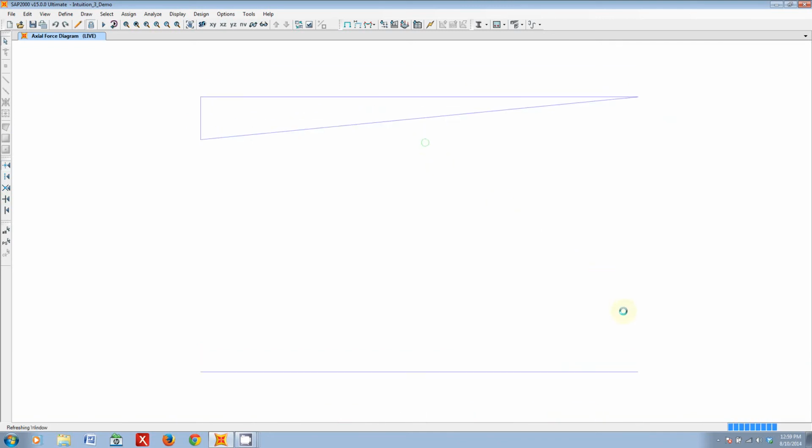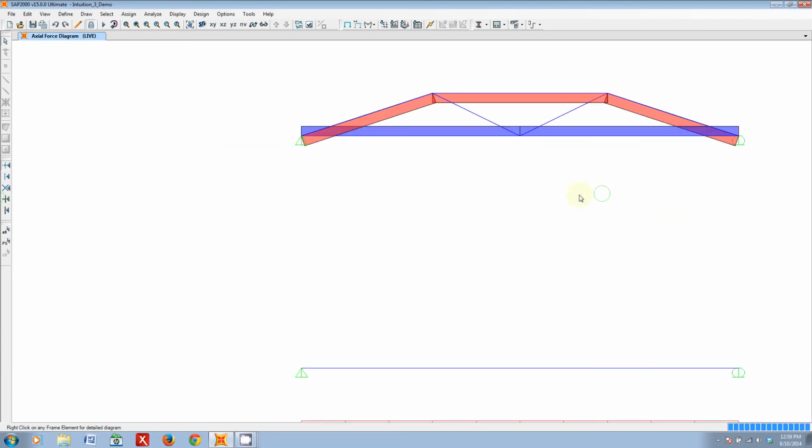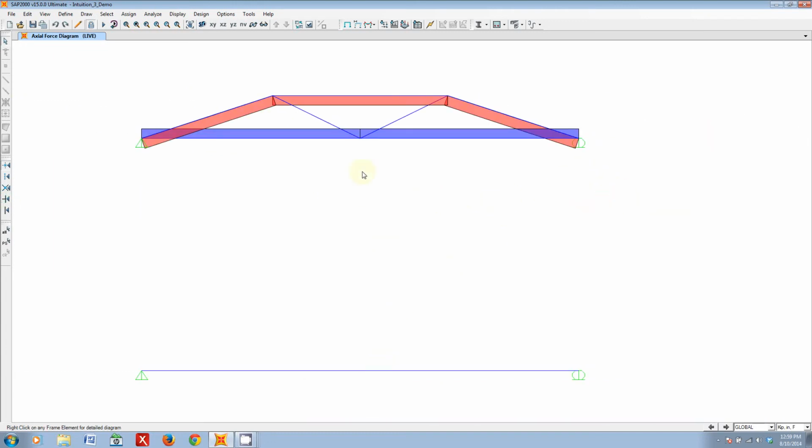Similarly, for our cantilever beam, we had 0 moment here and then a maximum here, so I'm just kind of drawing my truss to follow that moment diagram. And look at that, it looks really good. These are pretty much almost comparable forces. That's really great.